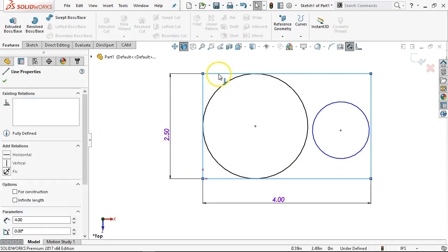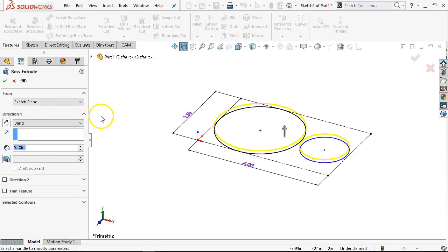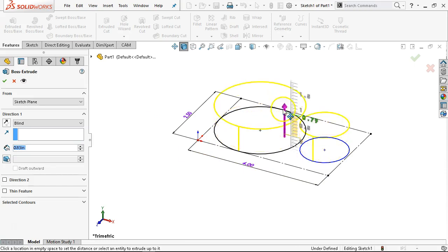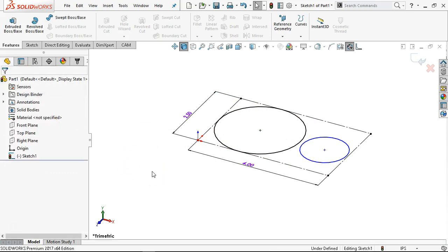And then I can right click and go to for construction and go to the extrude, and I see the preview and can drag the arrow, and because these are not nested, and they're not connected, I will end up with two bodies. All right. Also, discussion for the features, extrudes and revolves. But just be aware that when you see these two items, they're going to generate two bodies. All right. So we're not ready for that one just yet.